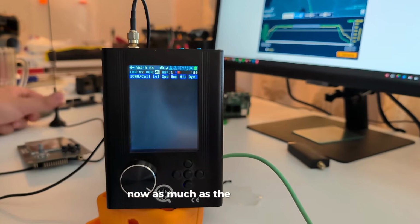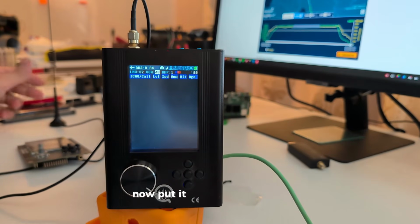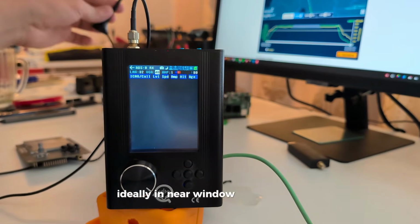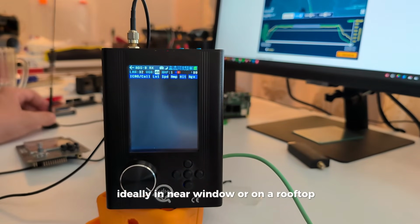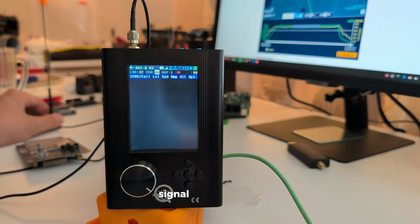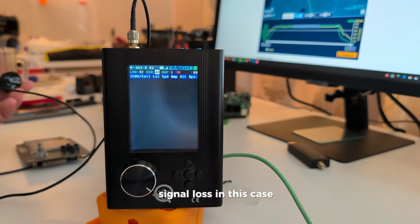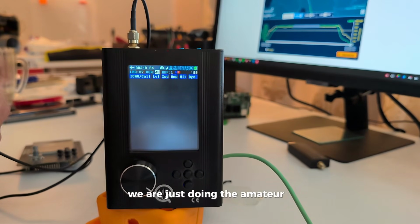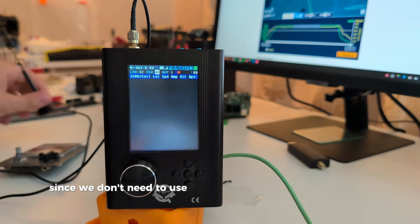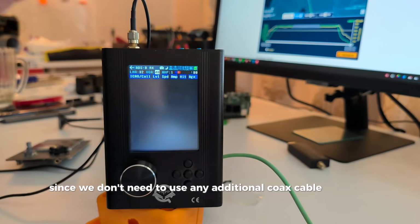Put it as high as possible, ideally near a window or on a rooftop, and use low-loss coaxial cable like RG6 or LMR-400 to minimize signal loss. In this case, we are just doing amateur software-defined radio, so we don't need any additional coaxial cable.